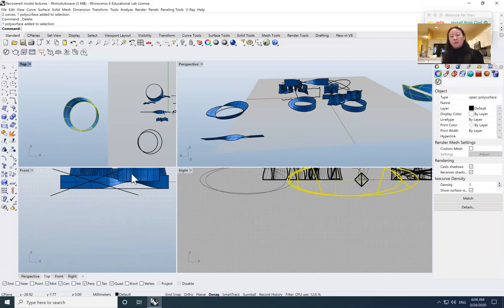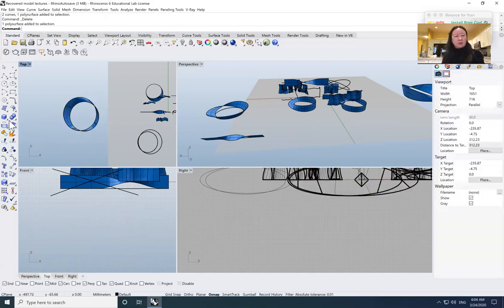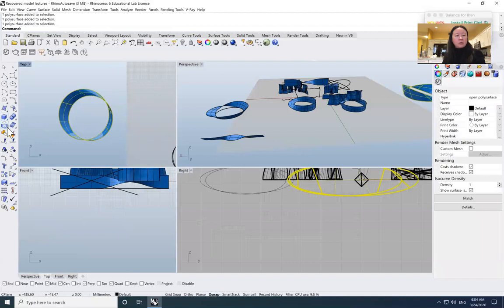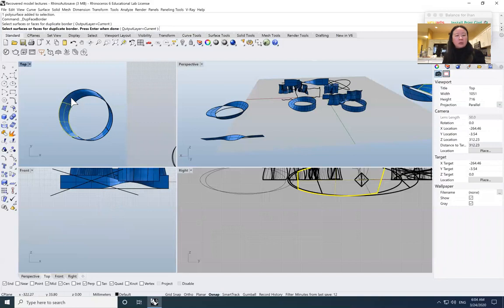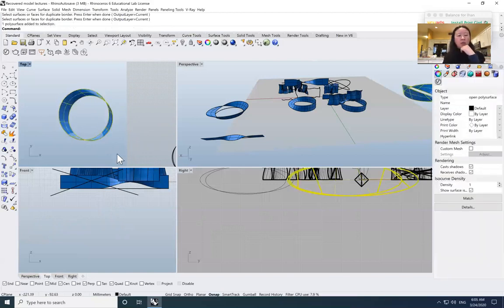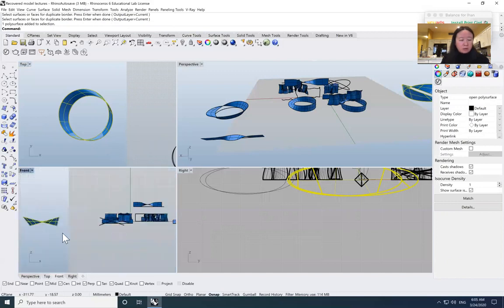Okay, why is it a poly surface? Even that should probably be able to. But it's okay because I have the circles in this case, so I don't need the edge. In case, for example, you want to bring out an edge of a surface, you can use this tool, which sometimes is very useful, except this is not altogether one surface, so you can choose all of them. So with a poly surface, even though they're together and can be selected together, they're not one surface. Since I have the circles still in there, I'm just going to use this one. Probably still a better choice.